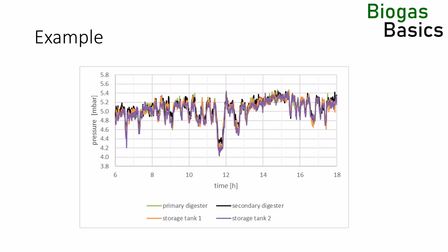A low pressure gradient is not automatically the case for all biogas plants, but this plant has a ring gas pipeline and was designed to minimize its pressure gradient within the plant. Nevertheless, keep in mind that the pressure in all gas domes rises and falls together.